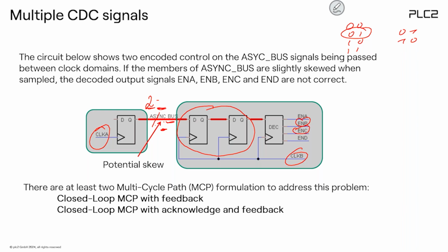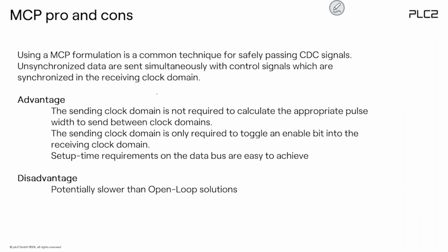And what really happened, I got also, instead of 0 1 and 1 0, a 1 1 in between. So this means I got this one here, and this is wrong. So be careful. You cannot do this. Whenever you have a multi-bit, you have to do something. You have to maybe have a feedback, or maybe you have to use, if it's possible here, gray coding instead of binary coding, just to make sure always 1 bit is changing, then it will be correct again. So be careful here. Okay.